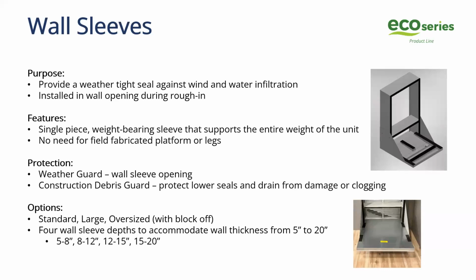There's nothing really that would freeze up on a heat pump or an electric unit, but obviously when you get into that condensing gas unit, that's when we need to make sure that we've got the temperatures appropriate in the closet. Yeah, so it's not insulated, but it is gasketed, and the design of it in general is to prevent against water infiltration, wind infiltration, and all of that.